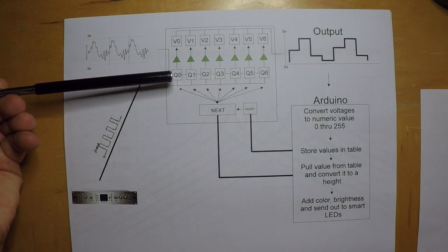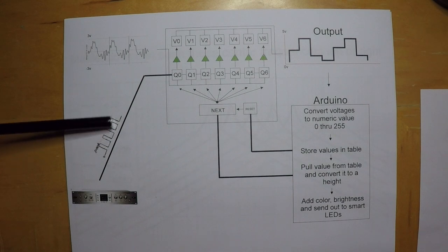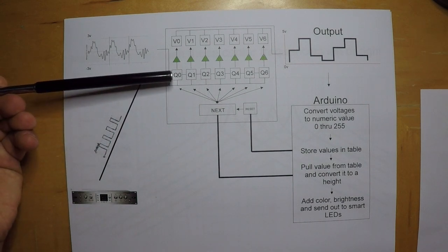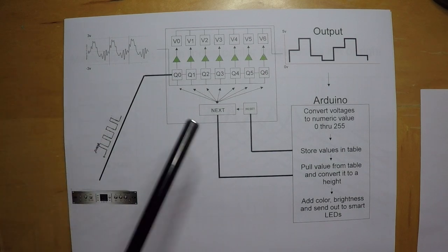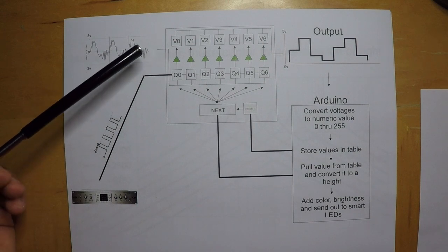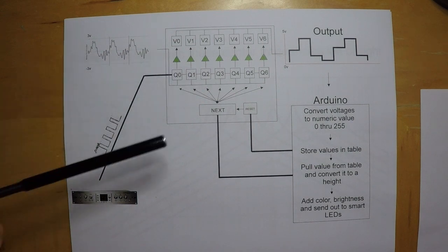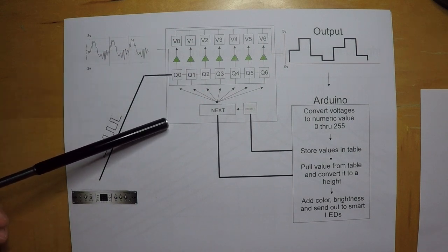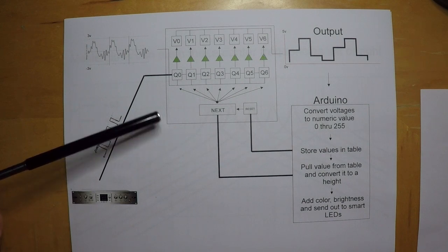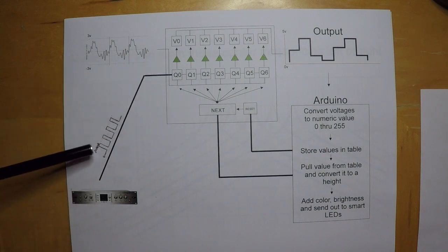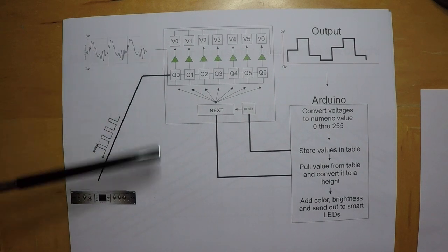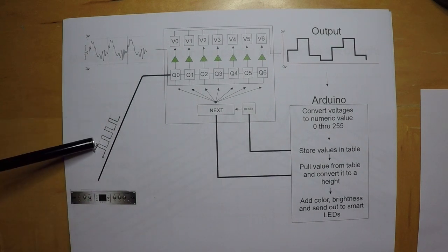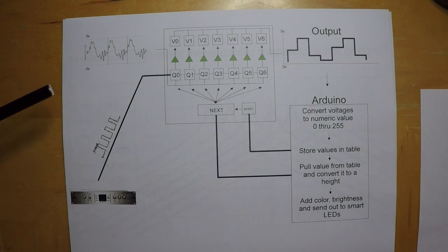Now, if I made each one of these pulses half the speed of what this is now, the frequencies would shift this way. And this is how we can have an analyzer that has more than 7 bands. What we'll do is pair up 2 of these slicer chips. One slicer chip will get frequency X, and another chip will get another frequency that has been skewed.